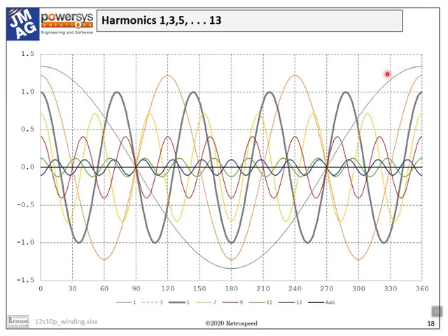Evidently, this is a subharmonic if we regard the fifth mechanical harmonic as the working harmonic or fundamental. In fact, when the three phases are working together, the first mechanical harmonic MMF component rotates in the opposite direction to the fifth. And the same is true of the seventh harmonic, this one.